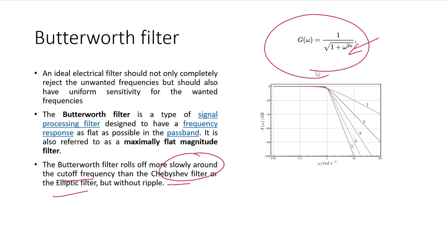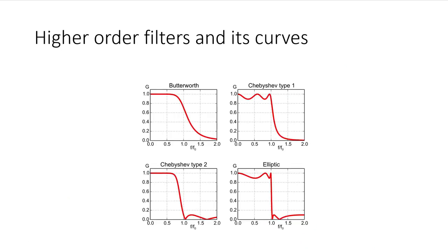So the Butterworth filter is something like this. If we use some other type of filter for high roll-off, and cut the signal like this, it will make the signal vibrate something like this. So Butterworth is the smoothest of all filters. We can check the higher order filters in these graphs: Butterworth is the smoother filter, but its response is slow.